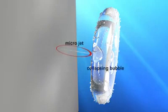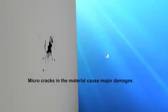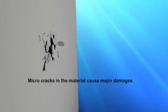The implosion releases energy in a very short time, concentrated in a very small spot. If the microjet hits a surface, it damages the material by a localized, short-term overstraining. The material starts to evolve microcracks, and later material can break off.